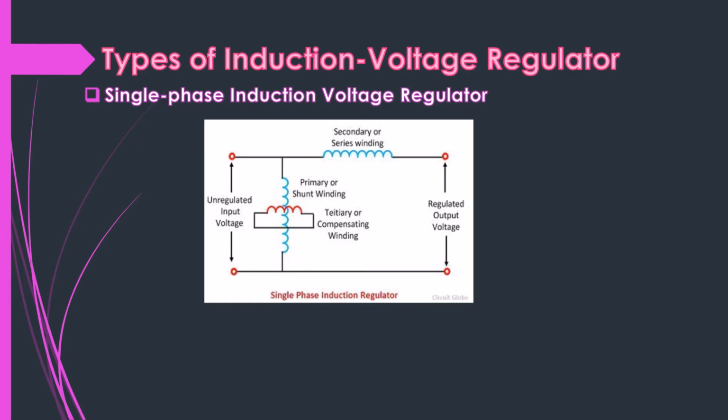The alternating flux is induced in the system, and when the axes of the two windings coincide, the whole of the flux of primary is linked with the secondary windings, and the maximum voltage is induced in the secondary. When the rotor is rotated through 90 degrees, none of the primary flux is linked with the secondary windings, and hence no voltage is induced in the secondary windings.